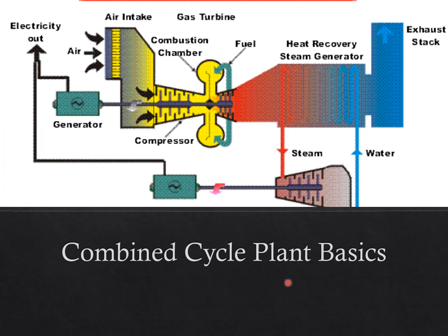Here is another diagram showing you the plant basis, and that's your high temperature combined cycle. You can see the steam out right here, and we are using the heat coming out from the exhaust, which you can see in this part. This is your HRSG, and that's your exhaust stack, and this is your cooling system because we're using water. It means that your material is not so advanced, so we still use the water to make sure the temperature is in the range we want, not so elevated.